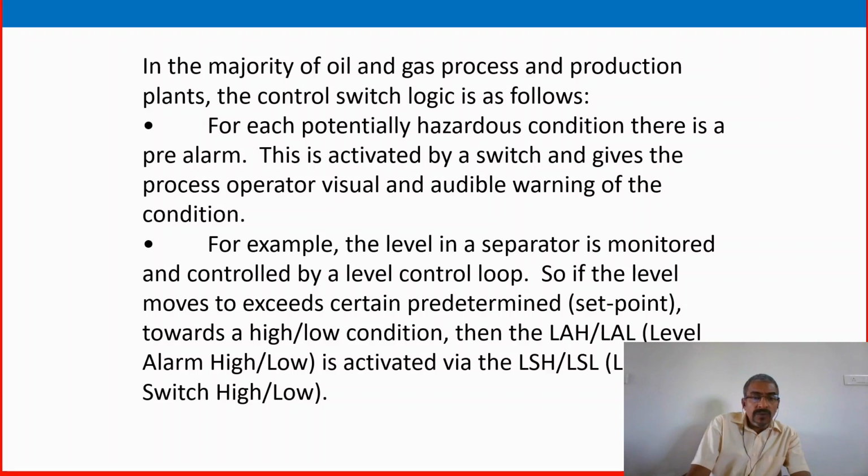If the level exceeds a certain predetermined set point towards a high or low condition, then the LAH, level alarm high, or LAL, level alarm low, is activated.